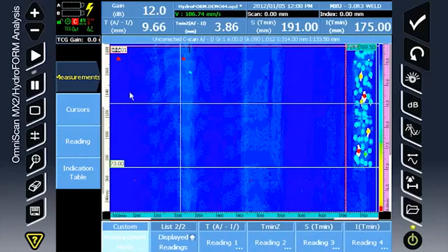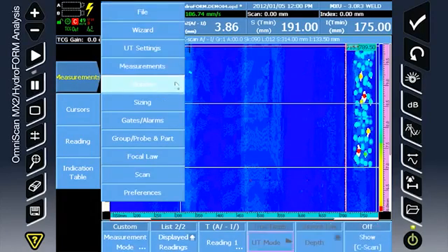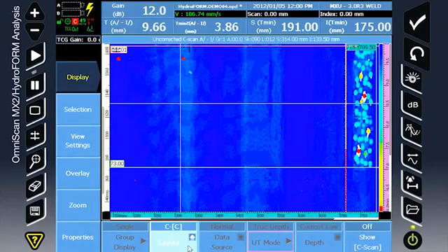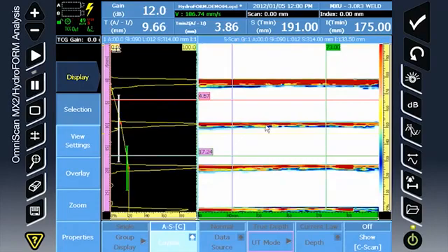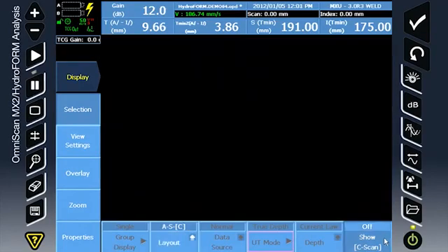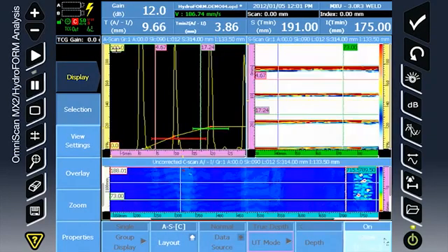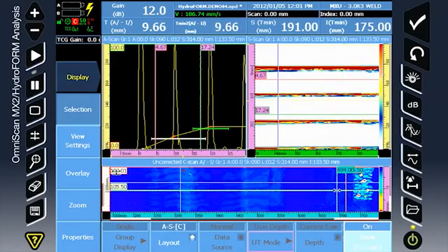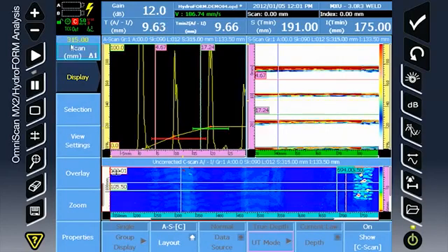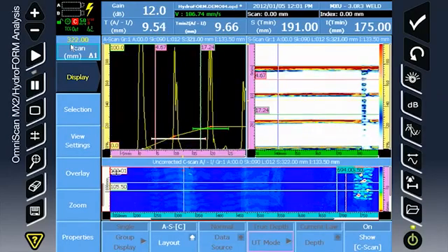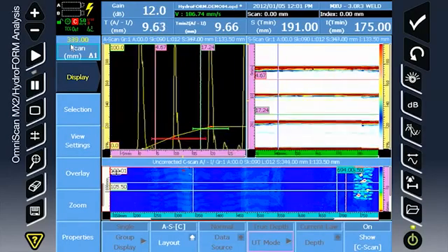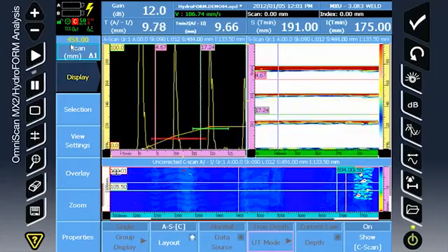We continue analysis by changing the display to the A, S, and C scan, activate the thickness C-scan, and here we'll see, selecting the data cursor and rolling through the data, we'll see the S-scan or type of B-scan, and we can visualize indications in the data.